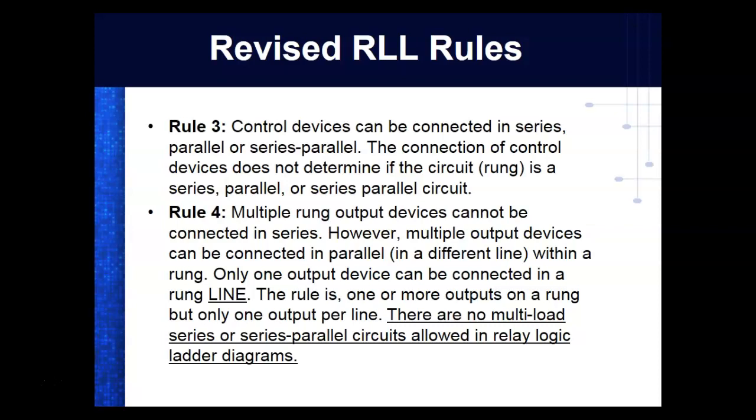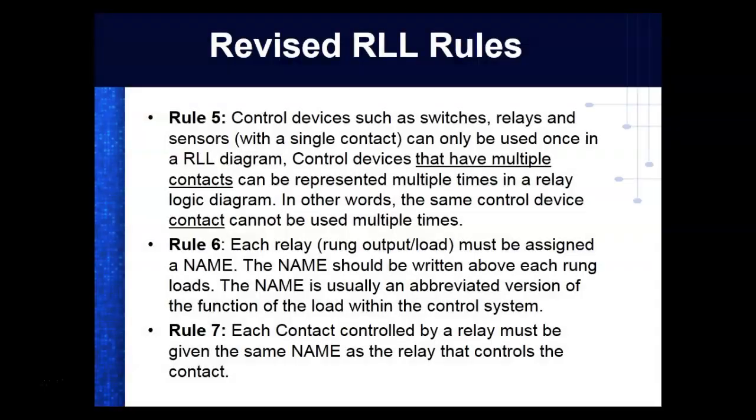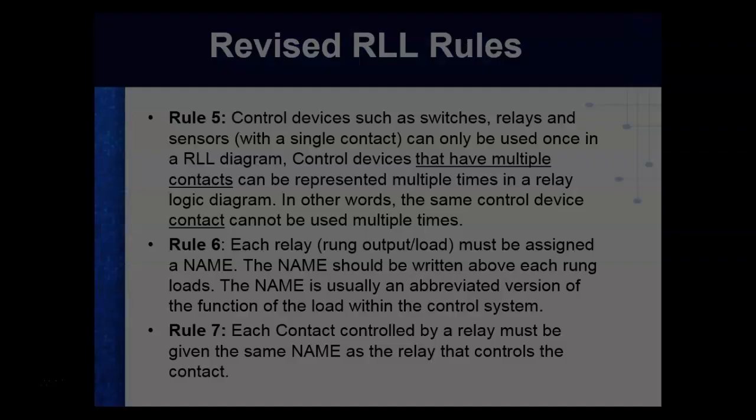There are some PLC programming applications that let you get by with this, but if it works here and doesn't work on another PLC, that's going to screw you up, right? So what we're doing is giving you the rules to follow for every PLC that you'll program. Rule 5, control devices such as switches, relays, and sensors with a single contact can only be used once in the relay logic diagram.